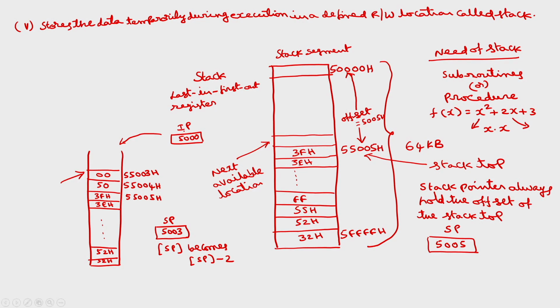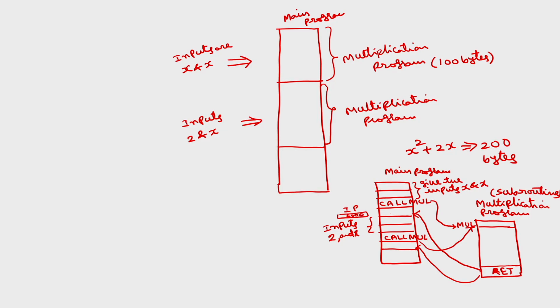The contents of the instruction pointer which will be pushed into the stack memory is internal to this call instruction. Whenever a call instruction is executed, the contents of the instruction pointer will be automatically pushed into the stack. In detail, I will discuss this while discussing the push and pop instructions of the 8086.